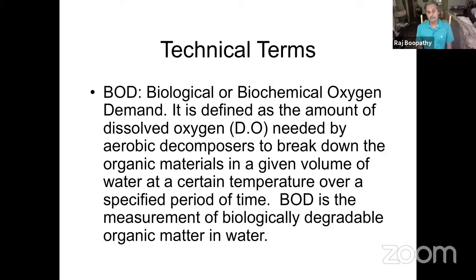So BOD is defined as biological or biochemical oxygen demand. It is basically defined as the amount of dissolved oxygen needed by aerobic bacteria to completely break down organic materials in a given volume of water at a certain temperature over a specific period of time. Usually, they incubate for 5 days, and they call it BOD 5, sometimes a 3-day incubation, at 20 degrees temperature to analyze how much carbon is in the water.